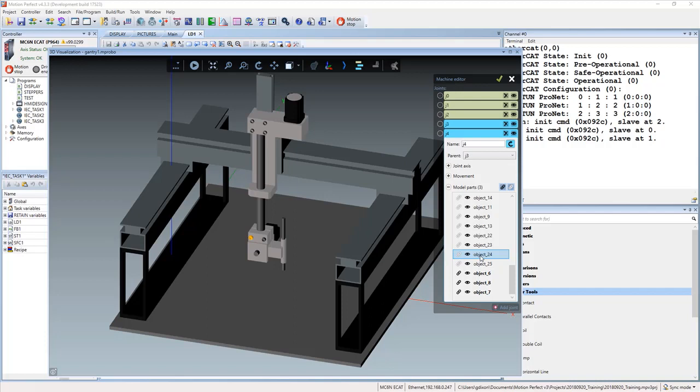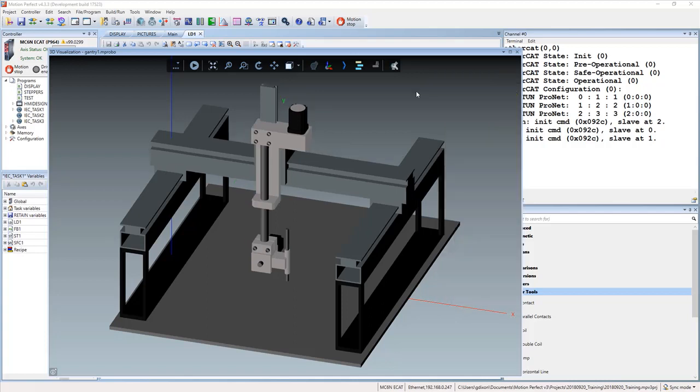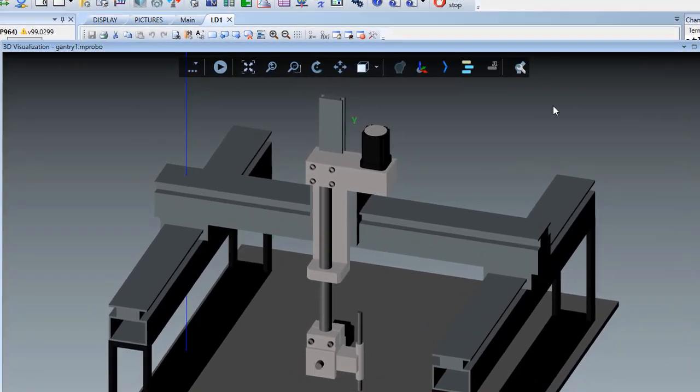And conversely, we had someone recently who provided a model where the whole 3D model was one object. Well, if it's one object, you can't separate parts out and animate them. So it needs to be thought about. Usually there's one OBJ file and one MTL file for the materials, and then you break it down from there.